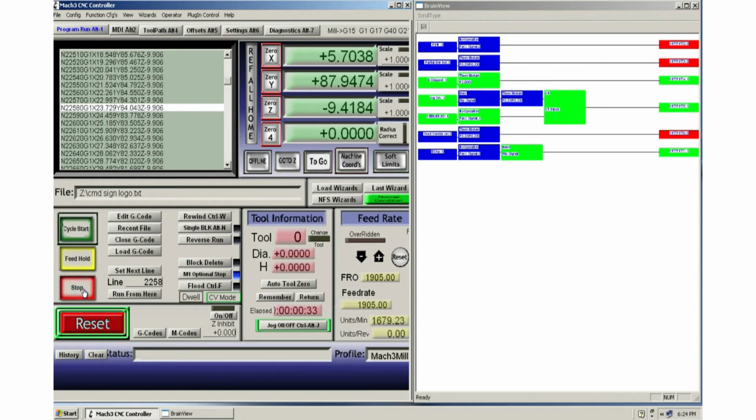If I click on the stop button, output number 2 becomes low, output number 4 becomes high for 2 seconds and then it goes low. If I click on the jog button, the first line of the instruction becomes high, making the timer flash the LED. If I click on it again, the second line becomes high and steady on. The last button or instruction is the feed override LED. Clicking on either override button will make it high, activating the timer and making it flash. Clicking on the reset button will become low again.